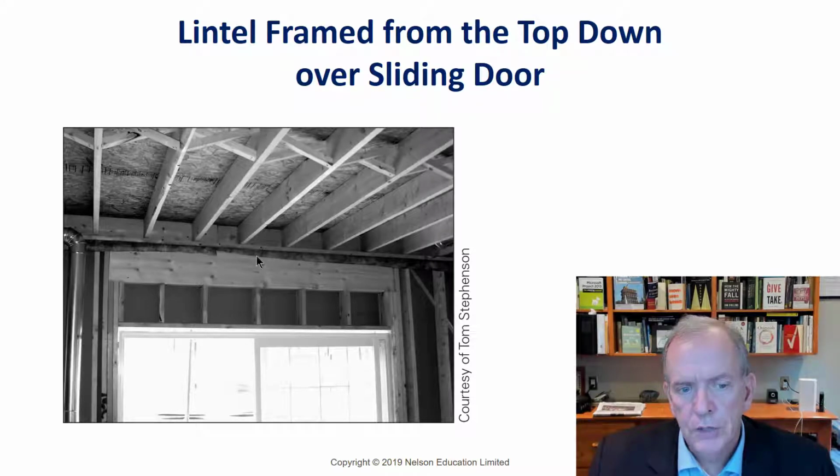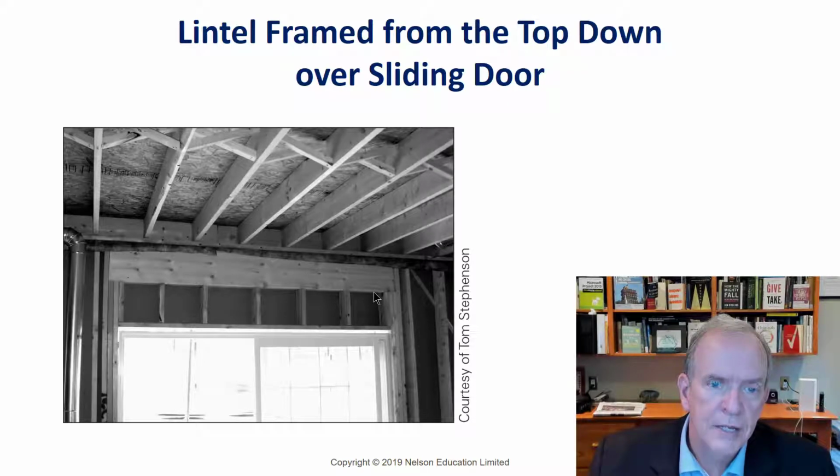This is also really good in wall framing practices, because there's a plate up here, and this particular opening, it's a 2x6 wall. It looks like three 2x10s for the lintel in this case. So three 2x10s would be 4.5 inches wide, 1.5 inches, 1.5 inches, 1.5 inches. Well, a 2x6 wall stud would be 5.5. So you have a 1-inch difference. That's about that little space you can see in there.